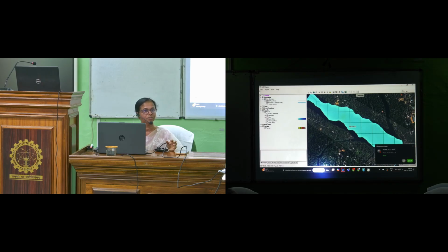No, no, no. We cannot take the entire area. It will take a long time because it is a numerical method that is based on the discretization scheme and the time step you adopted. Means we need the depth at hourly time intervals. So in that case, it will take more time if you give the entire watershed. So always select some particular area and do the analysis.